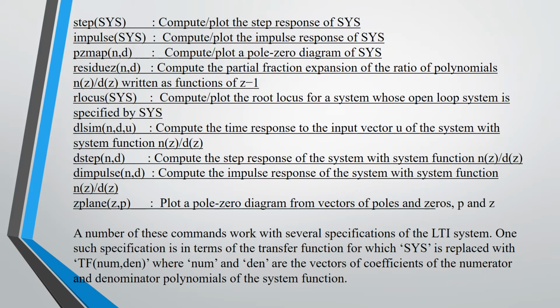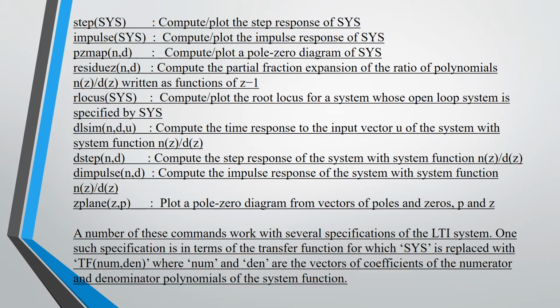A number of these commands work with several specifications of the LTI system. One such specification is in terms of the transfer function, for which sys is replaced with tf(num, den), where num and den are the vectors of coefficients of the numerator and denominator polynomials of the system function.